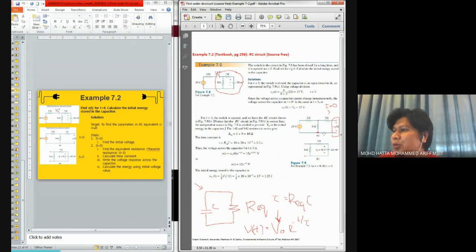So if you look at this solution, to find the capacitor voltage, i.e. the open circuit voltage, is basically finding the voltage across this 9 ohm resistor. So now we use the voltage divider rule to find the voltage across here, because the current over here is 0 and voltage VC is basically the voltage from this point up until this point.